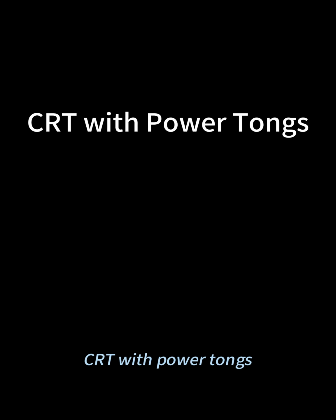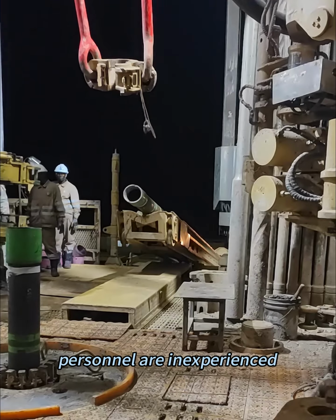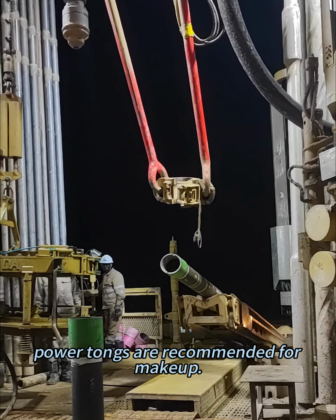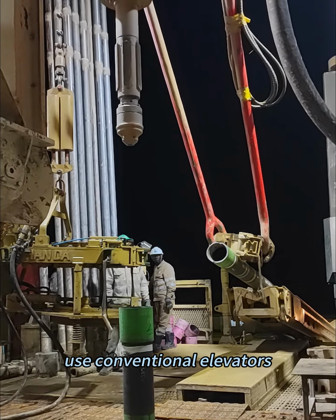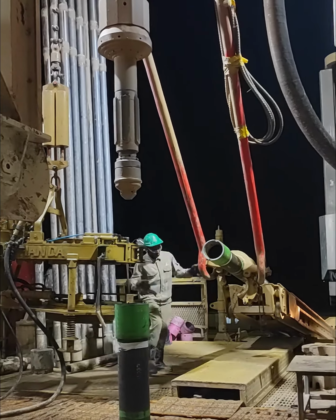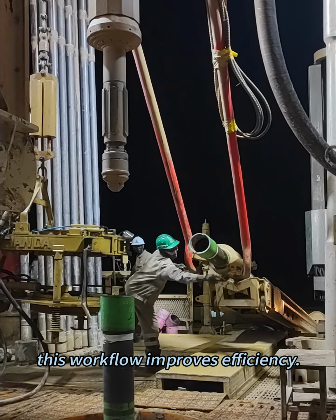CRT with power tongs. If the wellhead is misaligned, personnel are inexperienced, or casing cross-threading is likely, power tongs are recommended for makeup. After installing the CRT, use conventional elevators and slips for casing running. If resistance occurs, insert the CRT for mud filling and circulation. This workflow improves efficiency.